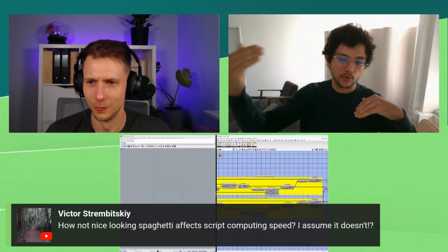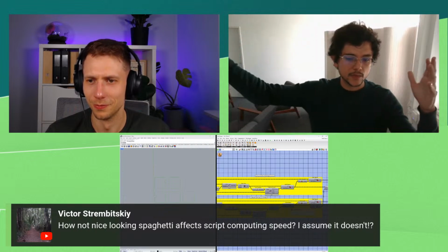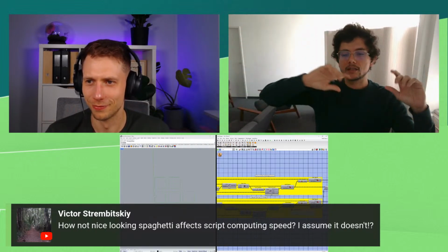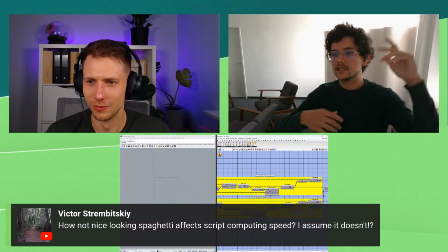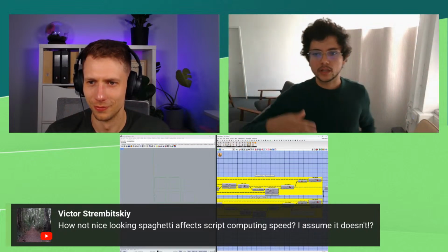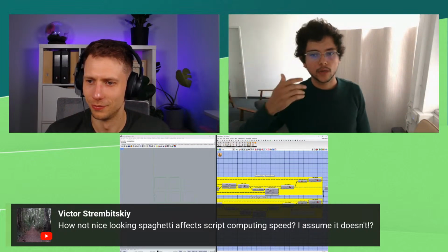So still for speed, it's important to not just go crazy and put in as many components as you have, but rather use data trees and clusters, so that you are efficient in how many components you use as well.